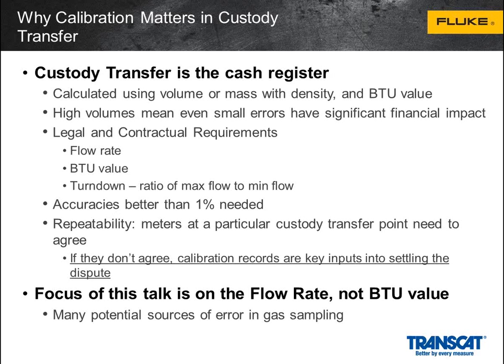So why does custody transfer matter? Or why does calibration matter for custody transfer? Well, custody transfer is, as the presentation says, the cash register. Fundamentally, it means that because we have such high volumes going through pipelines, even small errors are going to have significant financial impact. And there's a lot of contracts written around custody transfer. They're written around either mass or flow rate. They describe the BTU value of the gas to be transferred, and there's frequently a turn-down specification, that is, how much the maximum flow can be from the minimum flow. And these are all specified in legal documents.